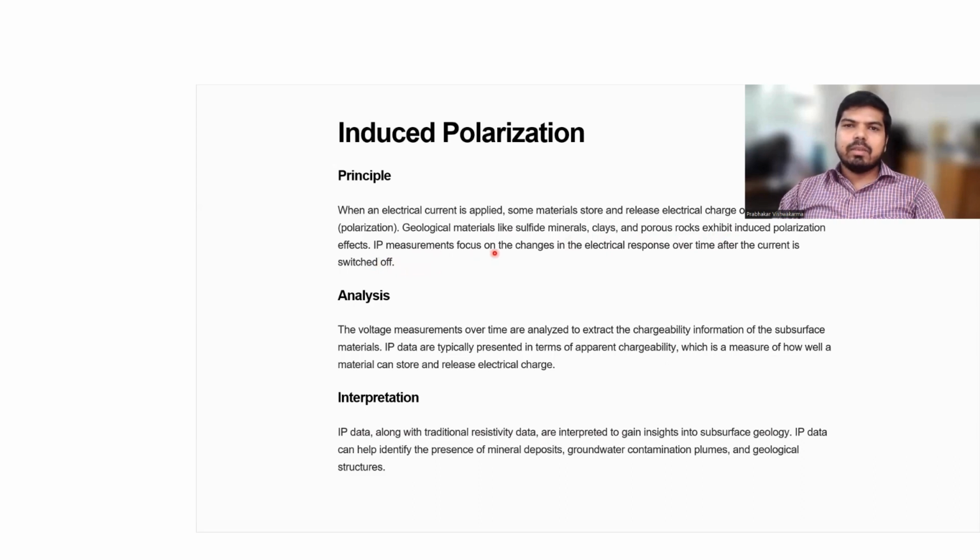Induced polarization measurement focuses on the changes in the electrical response over time after the current is switched off. So how is it analyzed? The voltage measurements over time are analyzed to extract the chargeability information of the subsurface material. IP data is typically presented in terms of the apparent chargeability, which is a measurement of how well a material can store and release electric charge.